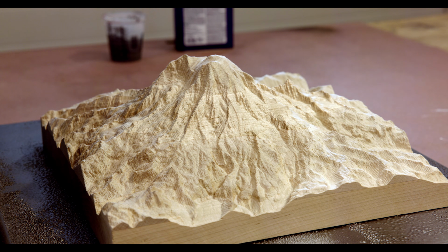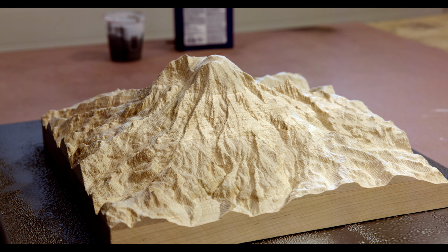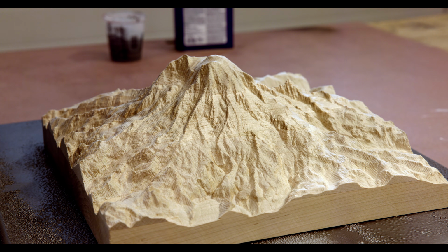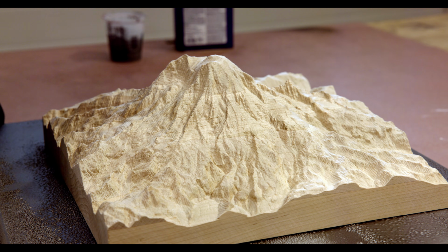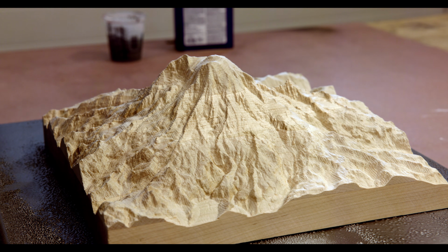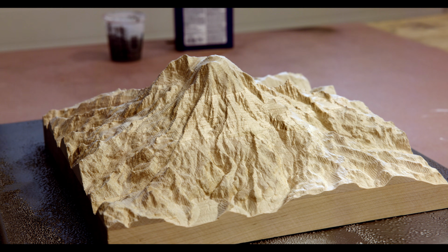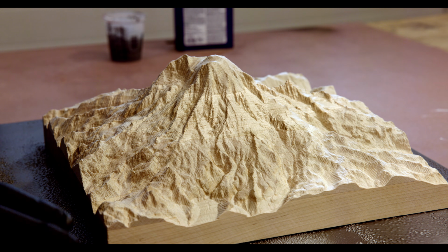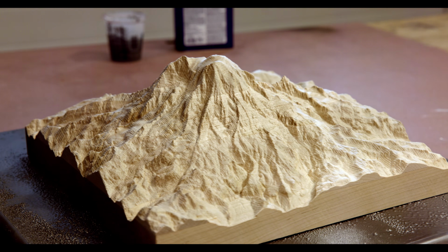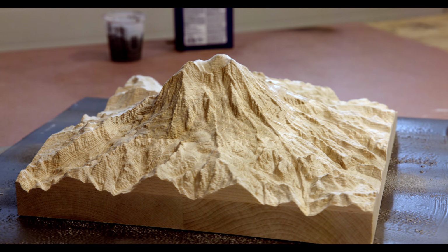Okay, so here it is, right off of the machine, and I've just taken it and gone over it with a steel brush, a stainless steel brush. I don't want to remove too much of the texture on the surface. I want to keep it as rough as possible. Going over it with a nylon brush will make the surface burnished and really polished. I don't want that in this case, so I'm leaving it kind of raw. And I'll spin it around for you there.